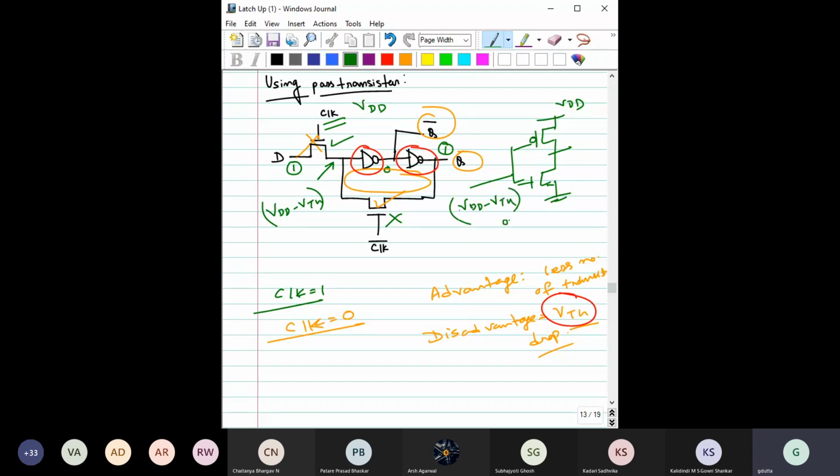Say this VTH is 0.6 volt. And the threshold voltage of this PMOS, say minus 0.5 volt. Then when you have applied this voltage at this input, what will be the status of this PMOS? Is it on or off? Slightly on, right? It has just 0.1 volt overdrive compared to the threshold voltage. So there is a possibility then this MOS is on.